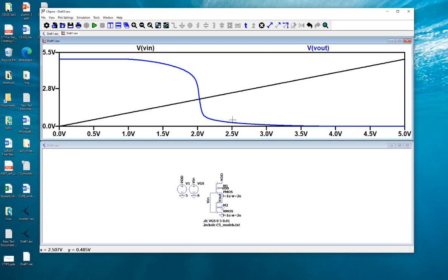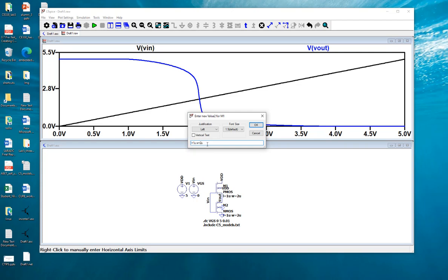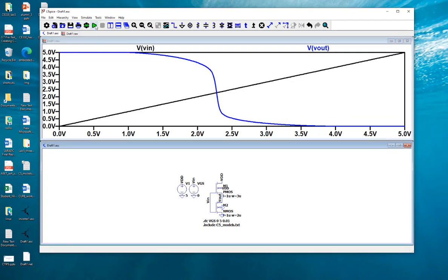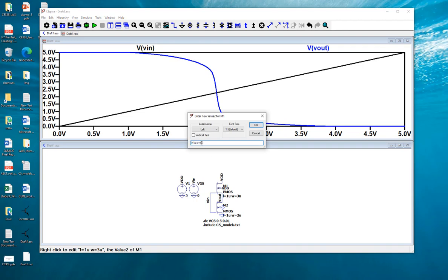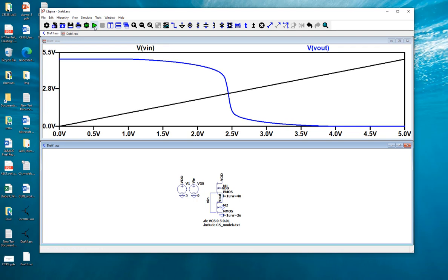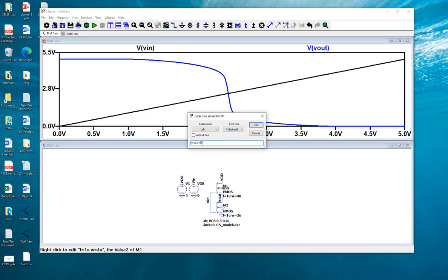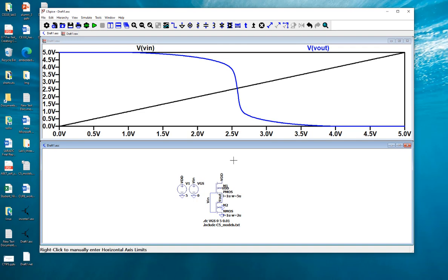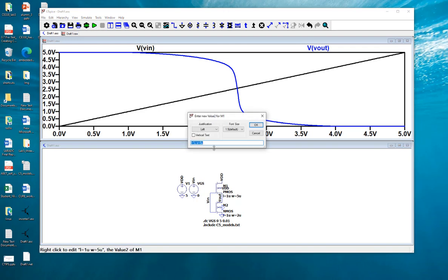PMOS should be stronger, so we should place Mike Tyson there, okay, instead of someone else. Okay, so in that case, we want to change what? Width to where? Just let me know. Yeah, more like 3, for example. Okay, 3 micron. Let's try it. Still not there yet. 4. Close. 5. Over 2.5 already, but I think should be 4, roughly 4.